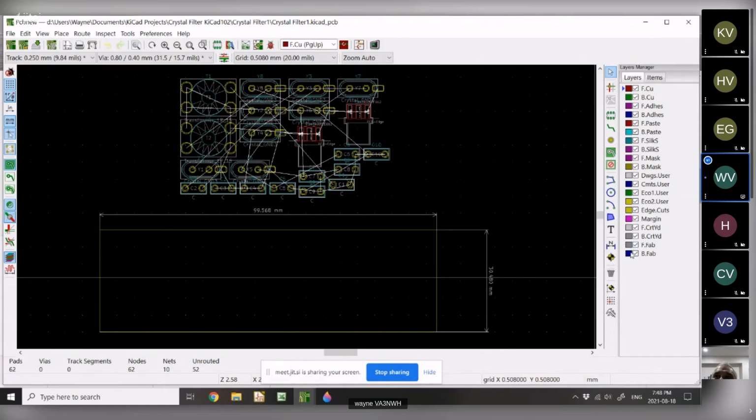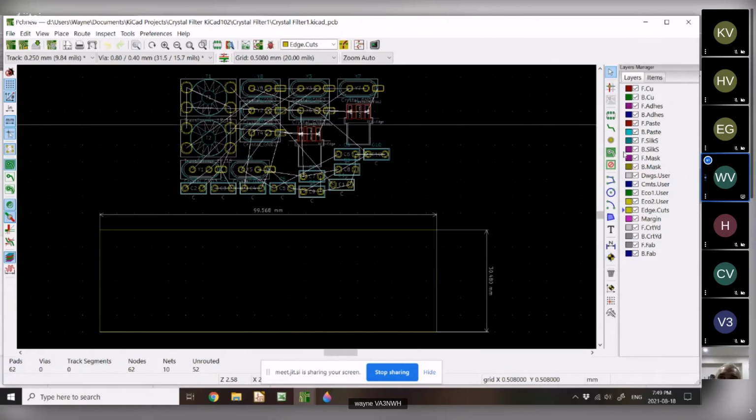So what I'm going to point out to you is you're not normally using most of these things. You're using the copper layers, this silk screen layer, and you have to use the edge cuts once. So for the edge cuts, if you click on it, that brings me to this. This is a toolbar, same kind of toolbar sort of thing that you saw in the schematic, except of course it's tuned for this. There's your line drawer. There's your fill in with copper. That's a filled zone thing. That's quite useful.